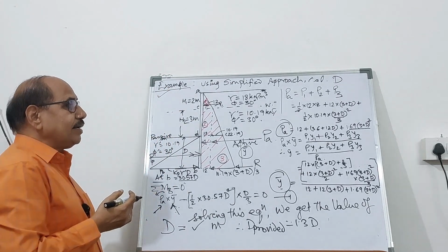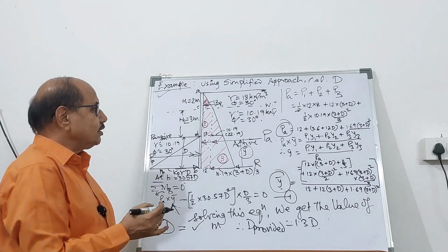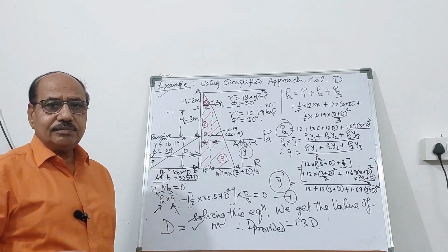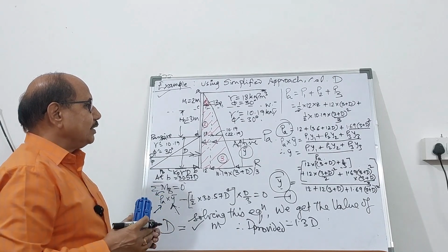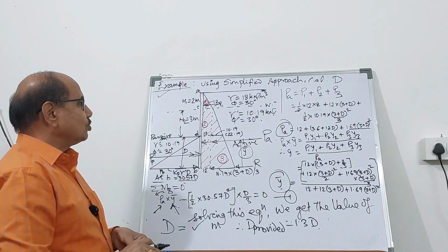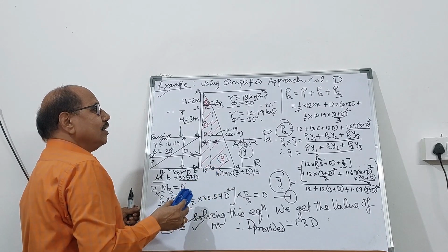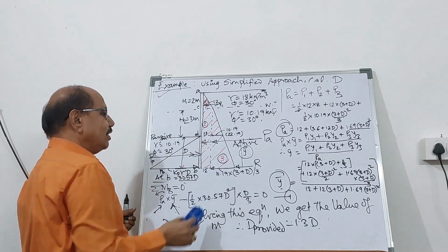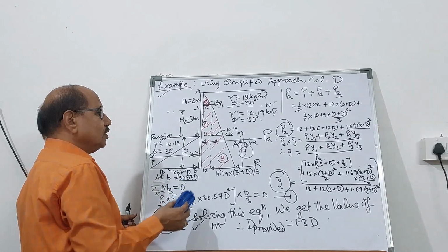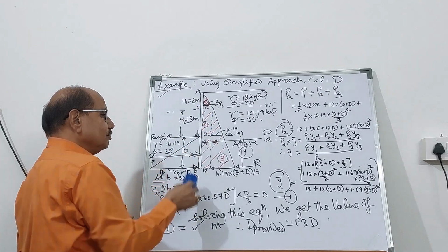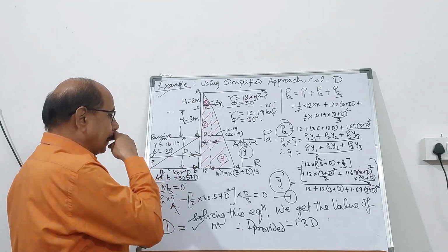So by the simplified approach, you get one equation. By taking the moment and pressure distribution diagram, you can easily calculate. So this problem can be easily calculated. It is simpler than your rigorous method in cantilever, where you have the pressure distribution, which is quite exact.